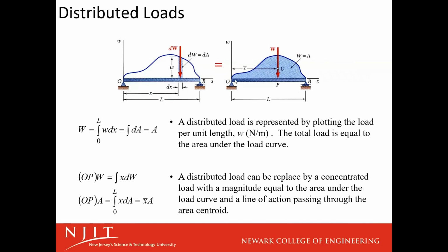Take the summation of all of that, and the area under the curve is going to be equal to the magnitude of the point force equivalent, right? So W is equal to the integration from 0 to L of each of those individual values to get a total weight equivalent. And that is going to act at the centroid of that profile. In this case, because we're looking at a horizontal beam, all of our forces are vertical forces, right?